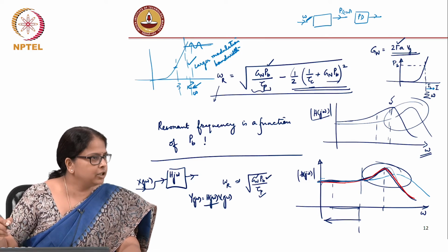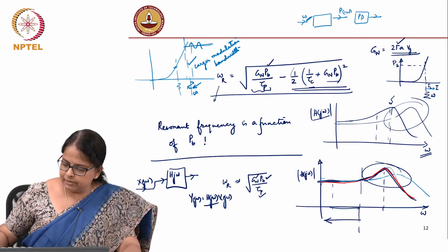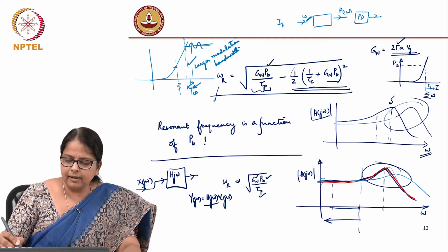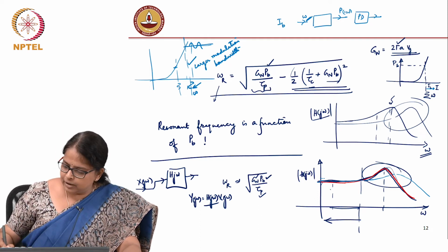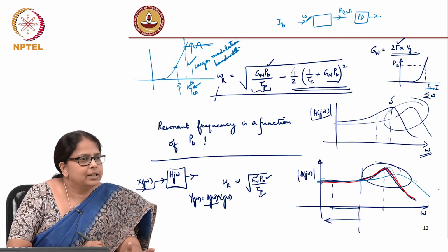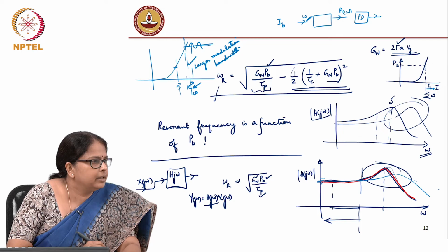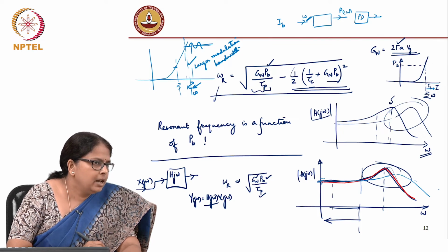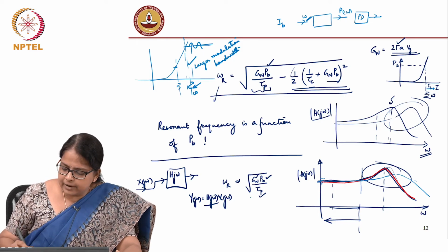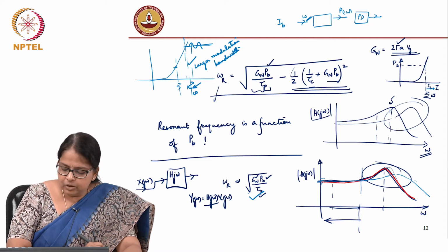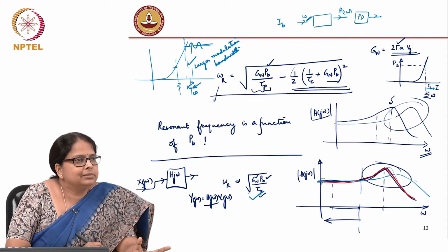So, with modulation to without modulation ratio, and find the transfer function, and you will have to repeat it at different Ib values to find out where your sweet spot is, and then figure out what should be the operating bandwidth. Okay.